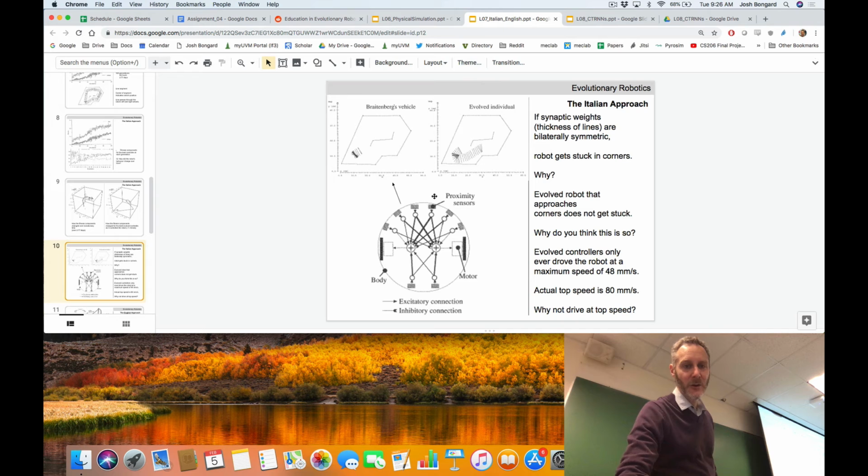So let's go back to our example here. We have an obstacle sitting right here, which means our right proximity sensor is firing strongly. And if we now follow one of the excitatory connections down to the right motor, it spins the motor on the same side so the robot ends up turning away. Exactly, right? So stimulation on the right passes through excitatory ipsilateral connections, causing the same side motor to spin faster forward. And the same sensor value is traveling contralaterally and inhibitory down to the opposite side motor, which is trying to get that motor to stop or even turn in the other direction, so it turns away from the obstacle.